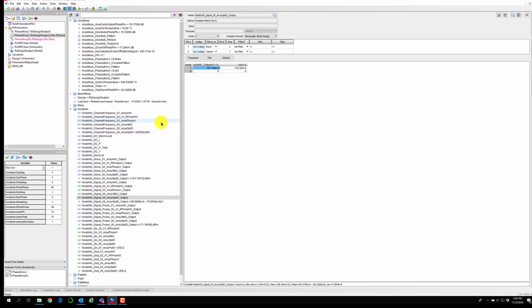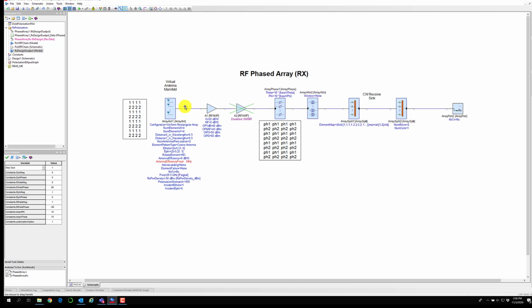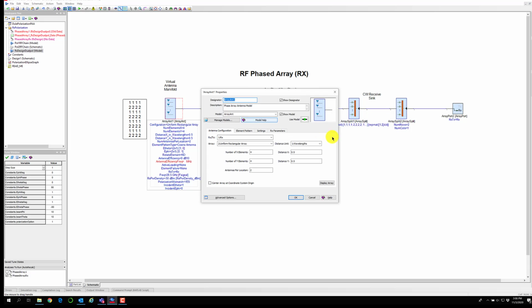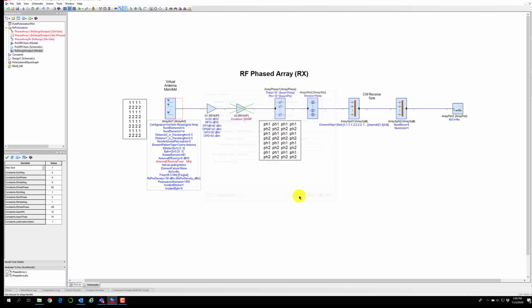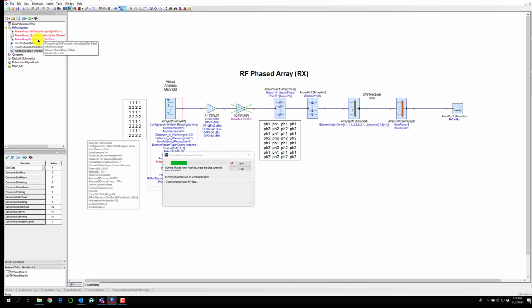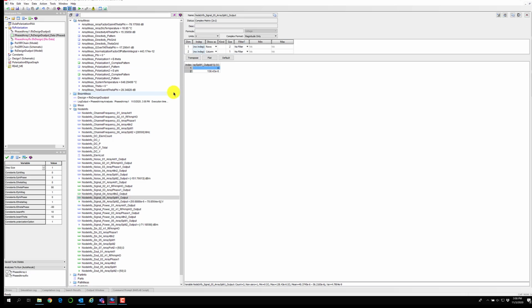You may ask, will I be able to get the discrimination if I switch the incoming wave polarization to the other one? The answer is yes. We can quickly examine that by reversing the incident wave and then simulating, and we now see the E phi antennas producing output.